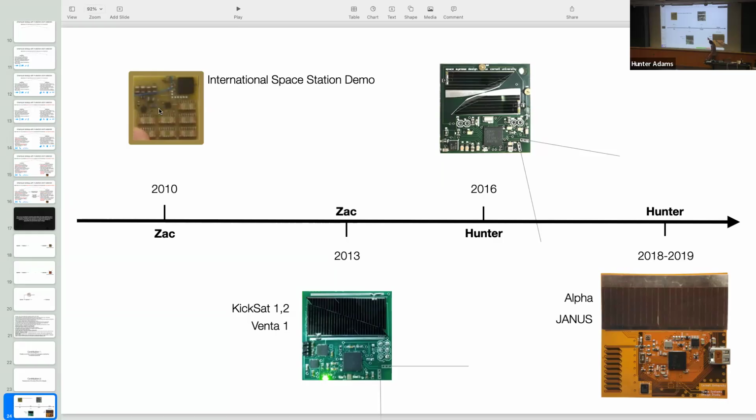2016, I would say, would be my first contribution to this sort of lineage. The modifications here included that this was a 2-layer PCB that became a 4-layer PCB. Embedded within the inner 2 layers there are loops of wire through which we can, by way of an H-bridge motor driver, move current this way or this way. You put current through a loop, make a little electromagnet, right?